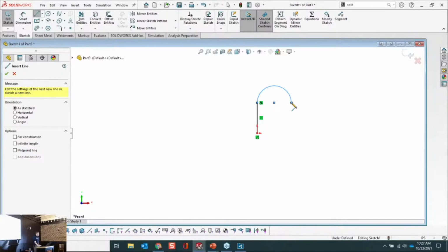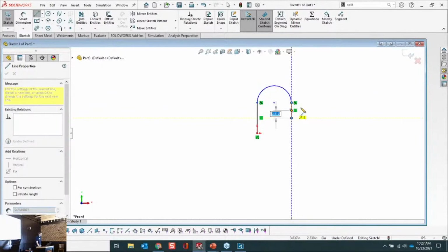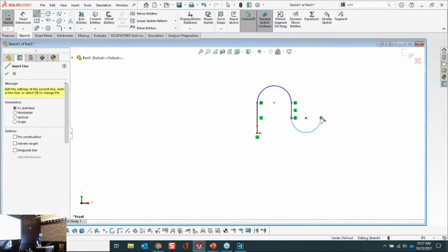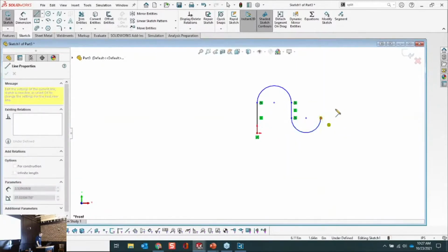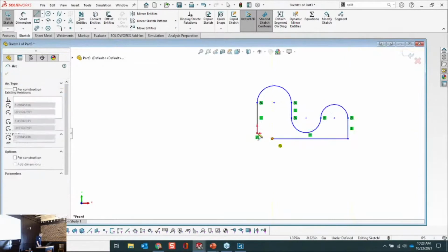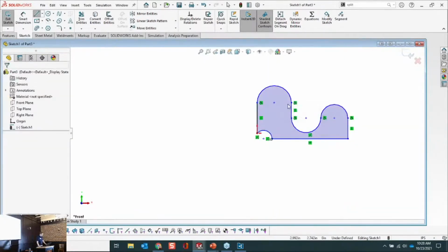Now, let's go even deeper. You can control this by rotating your mouse. So if you rotate out and go clockwise, it'll go this way. Go counterclockwise, this way. As long as you go back to the center, you can really create any arc you want. You can even go arc on top of arc. You just have to come back to it. This allows you to make all those crazy geometries that you absolutely hate quickly. And it does add tangency while you go on the fly there.